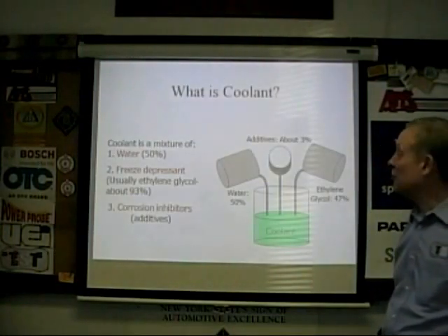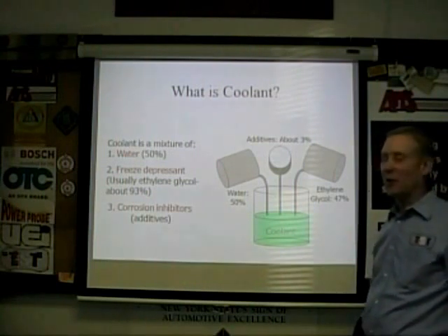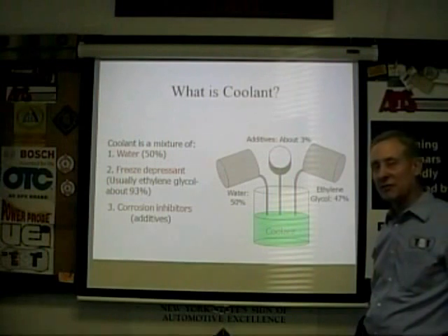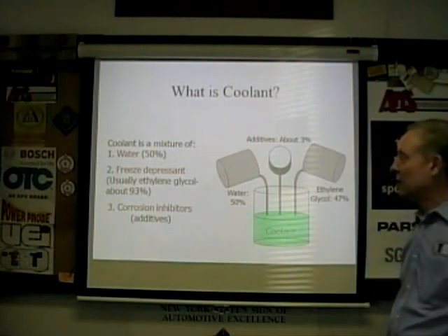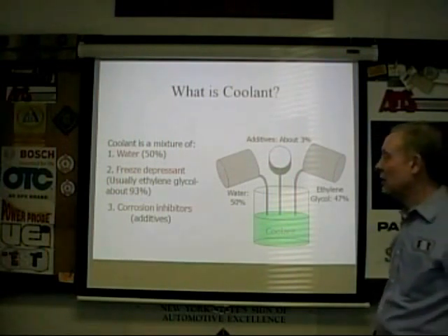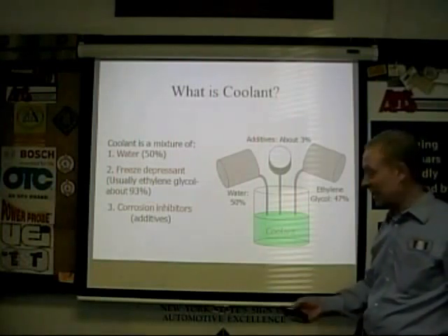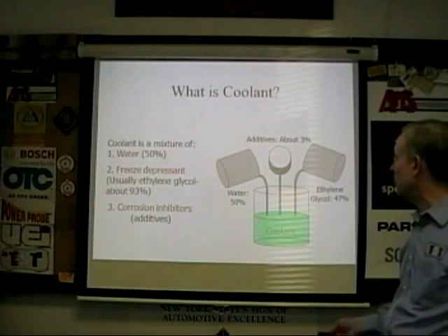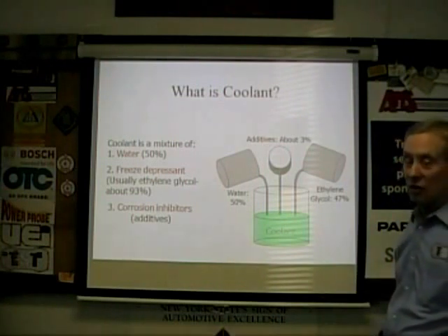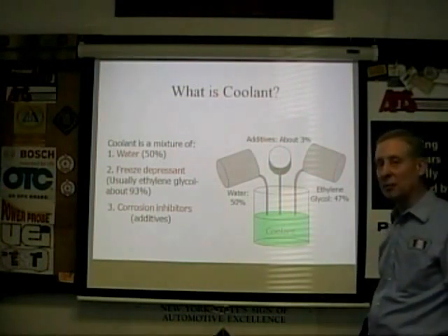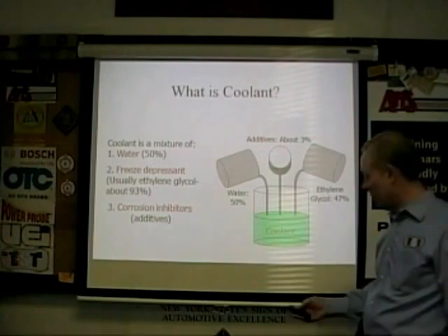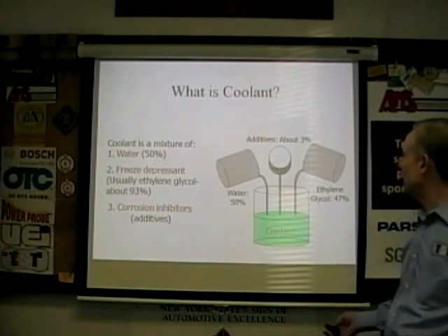All right, what is coolant? We all think we know this. Basically, it's generally a mixture of between 50-50 and 60-40 ethylene glycol and water. There are some propylene glycols, we're going to get into that, but for us it's ethylene glycol and water. There are other additives, water pump lubricants, rust inhibitors, and other additives that we're going to go into.